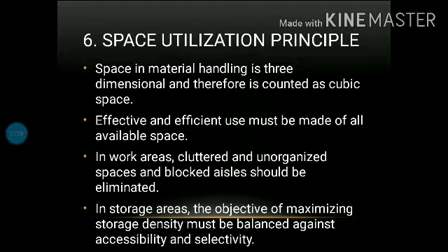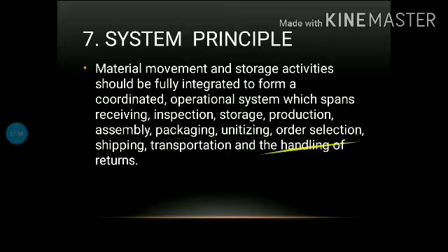Space in material handling is three-dimensional and therefore is counted as cubic space. Second one, effective and efficient use must be made of all available space. Third one, in work areas, cluttered and unorganized spaces and blocked aisles should be eliminated. Fourth one, in storage areas, the objective of maximizing storage density must be balanced against accessibility and selectivity.